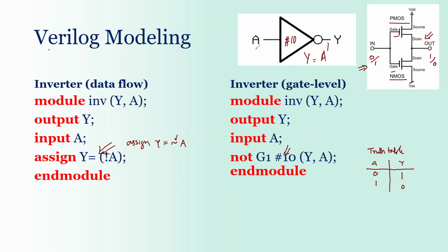So it means when switching at the input from 0 to 1 or vice versa takes place, it will take 10 nanosecond or 10 units of time to reflect those changes at the output from 1 to 0. I say again, it will take 10 nanosecond, that is the inherent propagation delay of a NOT gate or any logic gate for that matter. So when you have a switching at the input, there will be switching at the output, but it will be after the 10 time units. It depends on nanosecond or picosecond. That's why you can define the delay, that is the propagation delay.